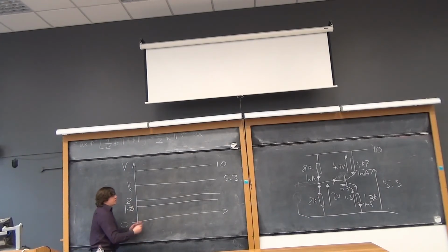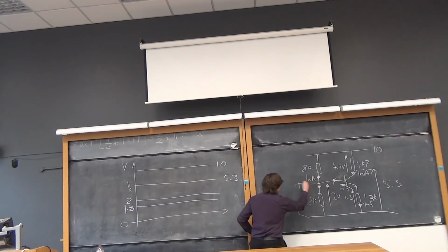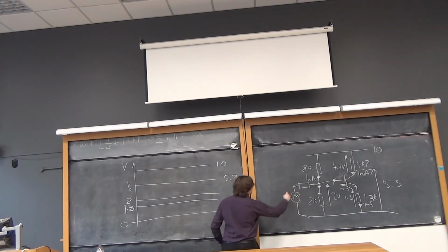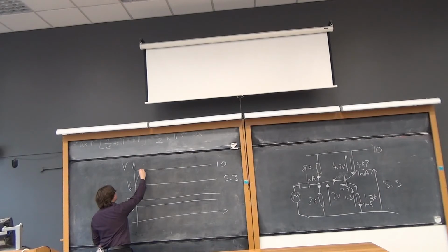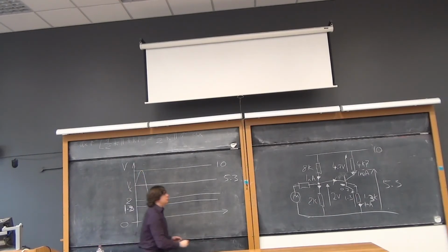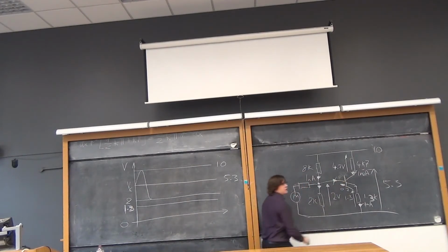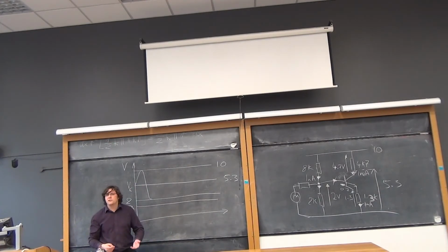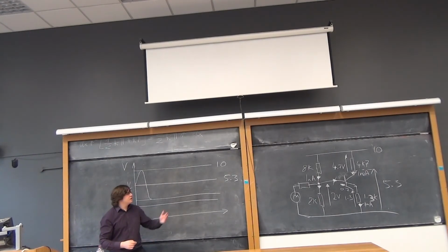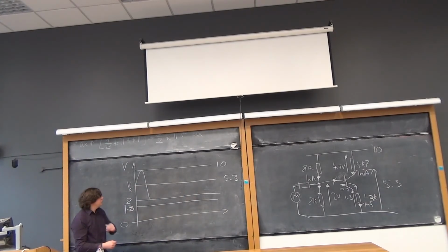So if I put some signals into this circuit now, by driving it with a Thevenin source, there is some maximum value that I can use. And that value will be the value that drives a signal that just about touches the supply and just about touches the point where there is no voltage across the collector base junction, because that's the point at which it's likely to start turning on. We need, say, 0.7 volts to turn it on. You can't have the collector drop much below the base, otherwise you risk getting into saturation, into switching mode.